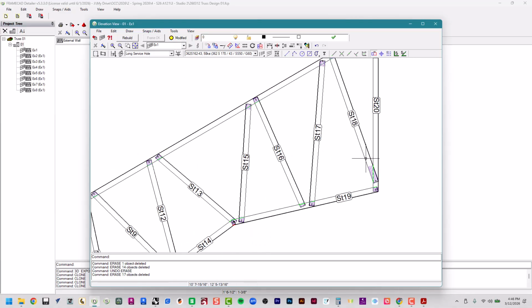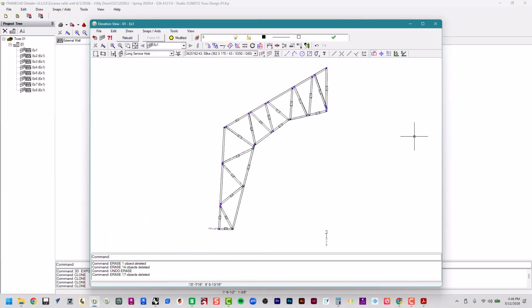And if I need my dimensions back, say place dimension, I can hit enter, and then the start coordinate would be down here, going to here, right? Or if I hit escape a couple times and click this, I can say let's do automatically create dimensions. I can hit enter, select objects to dimension, hit enter, start coordinate here, here, here. No, that's not it. That was wrong.